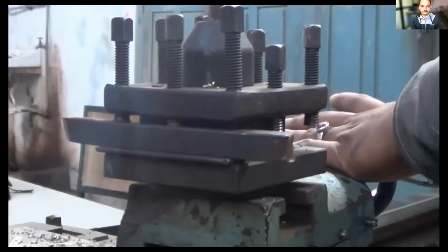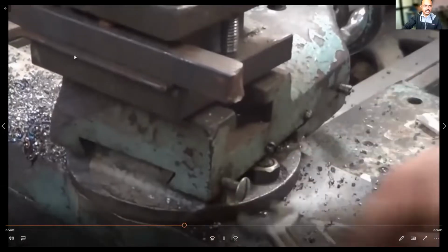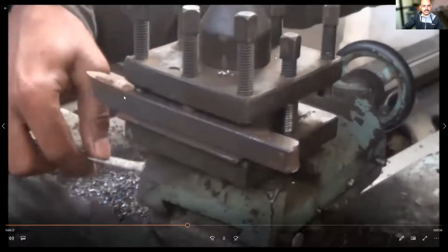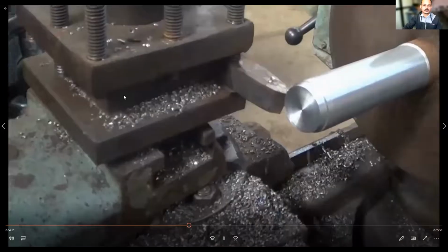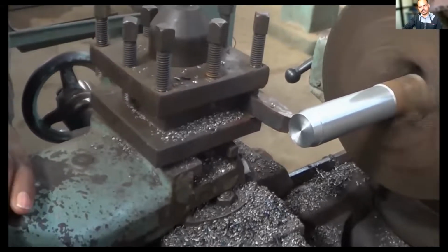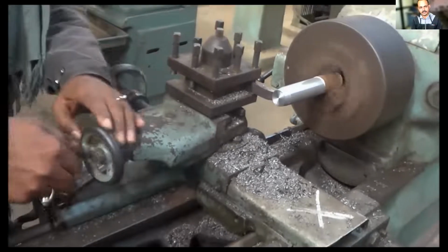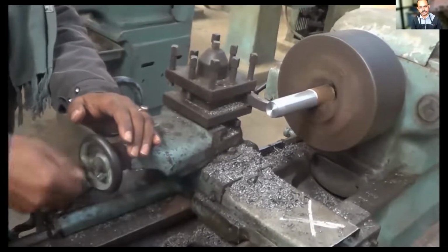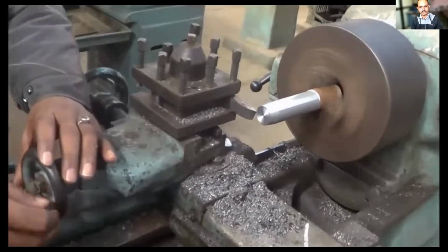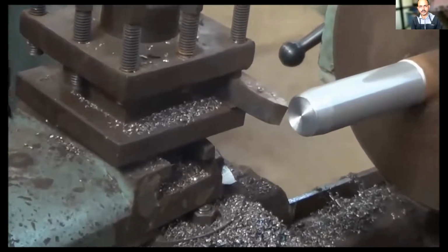Now, after the turning process on a specimen, we have to rotate the tool post. This is the tool post, and the tool is fixed in it. In this process, it is required to rotate the table at some fixed angle according to the operation. With the help of the slide wheel, we slide the carriage toward the job by hand. The feed is given by using the cross slide and compound slide, and we can perform this taper turning operation.